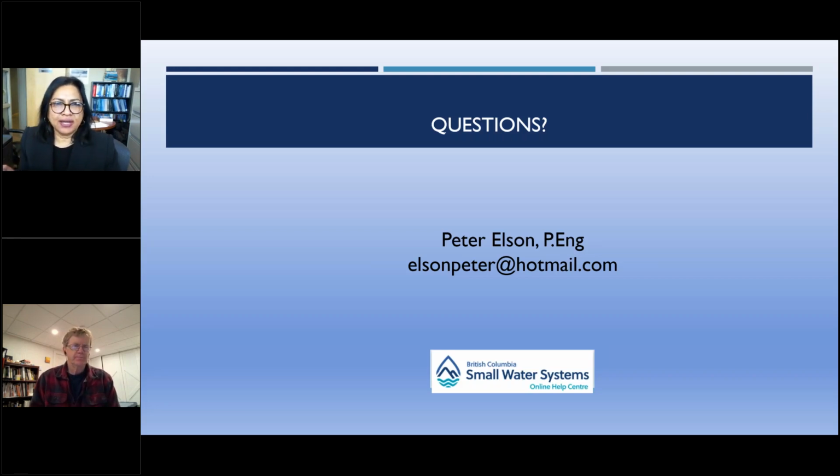Just going back to Darnell's question on manganese. Darnell, I hope Peter was able to answer that. I thought that was a good answer: checking your raw water, checking your treated water, checking the reservoir, and then having a couple of testing points within your distribution system. I hope that helped. I thought that was an excellent start. Next question, Peter.